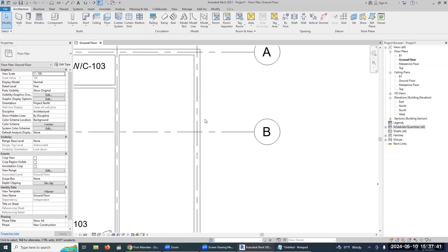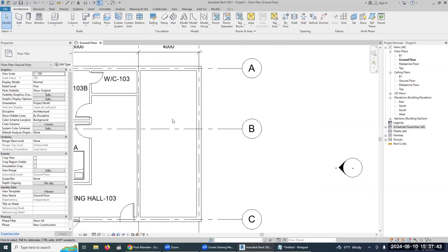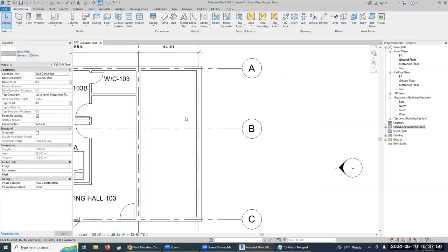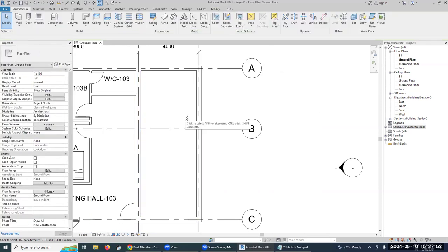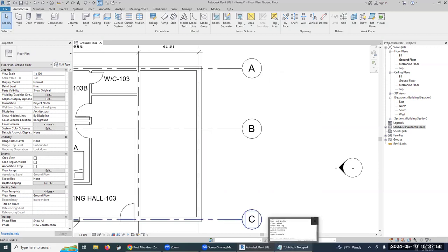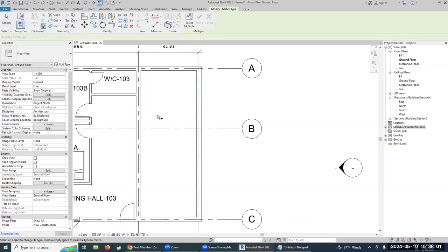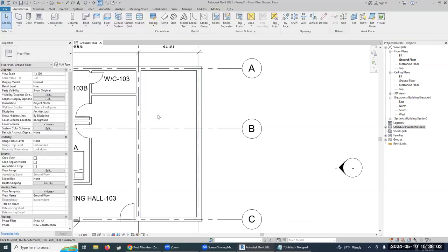See here, there are several methods. One method, just check it. This is how much? 300. Select it and change to 300. This is one method. Another method, you know, in AutoCAD, match properties. What do you type? MA. And select this and select this. This is match properties. MA or MP? MA, no? Yes, MA, match properties. So either this way. Okay.